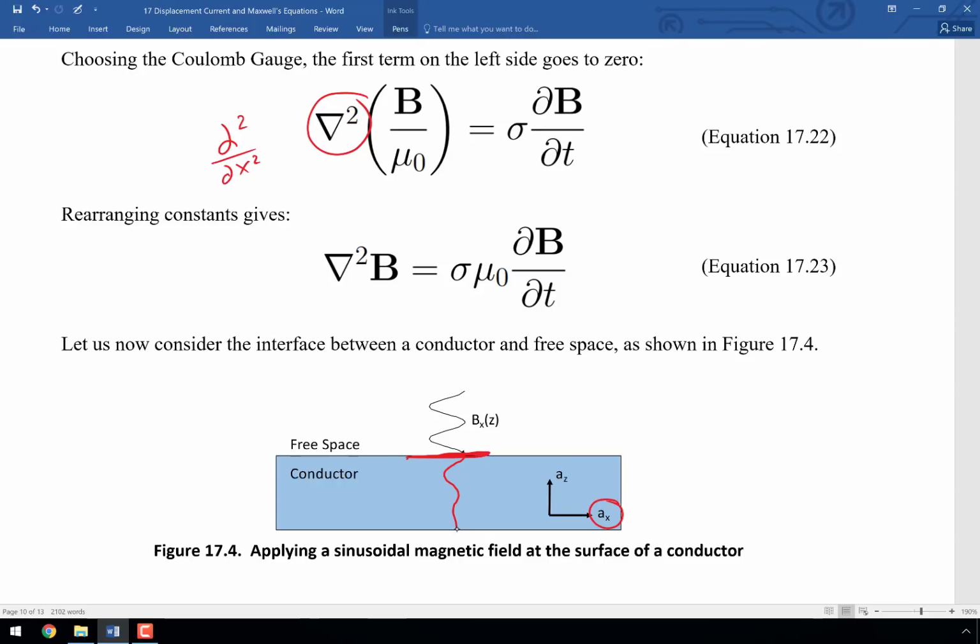Well, the magnetic field is causing electrons to circulate inside the conductor. Remember, a conductor is nothing other than a sea of electrons, free charges that can respond to anything. And they're all responding to the Lorentz force that's created by this magnetic flux. As they're spinning, what does Lenz's law say? That the induced magnetic flux is going to oppose the applied magnetic flux. That weakens it, and then over a relatively short distance in most cases, it's going to approach 0.